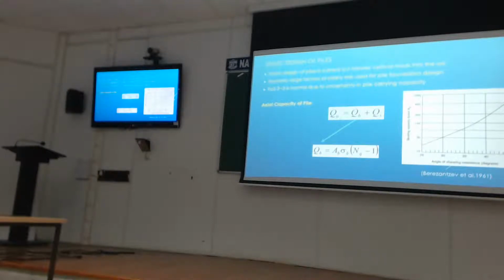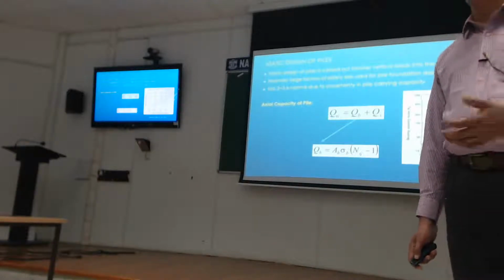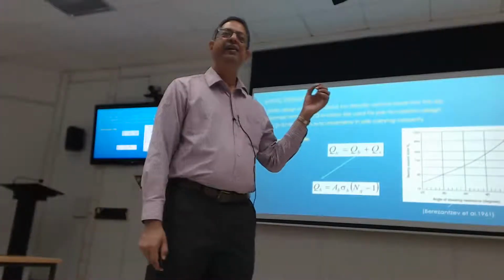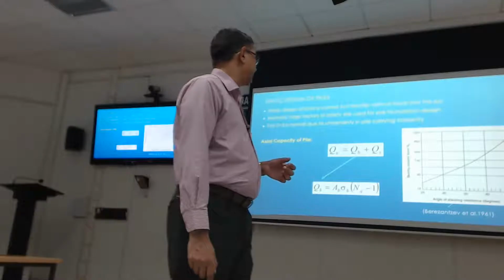Whereas with your real soil, you design this, give it to your pile driving contractor, and they can't put the pile in the first place, they'll come and blame you. What kind of engineer are you? You said that you need such long piles, and we can't go. They reached what they call the refusal depth quite quickly. So you lose face. So don't do that. Have a good estimate of the material properties.